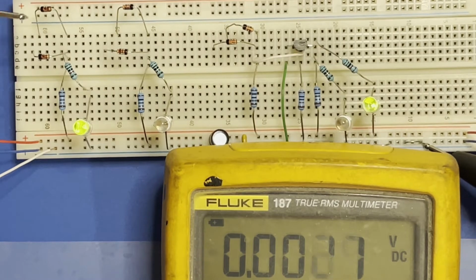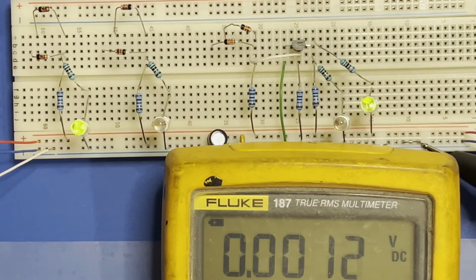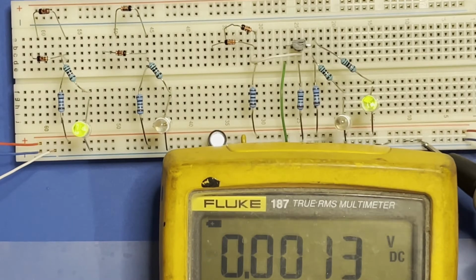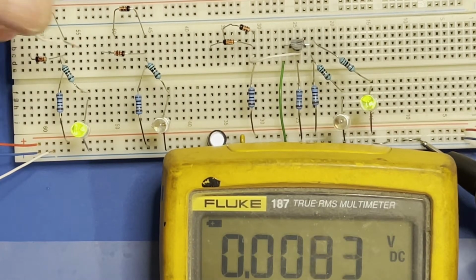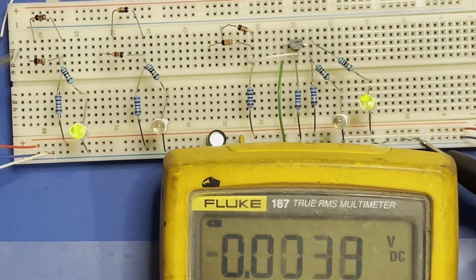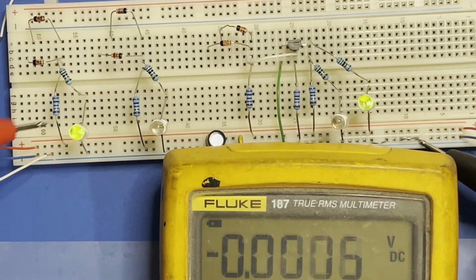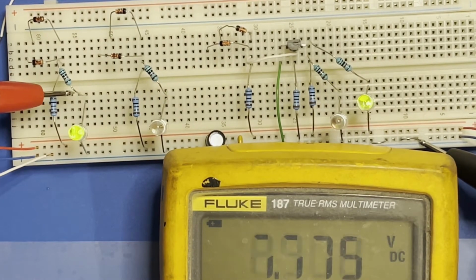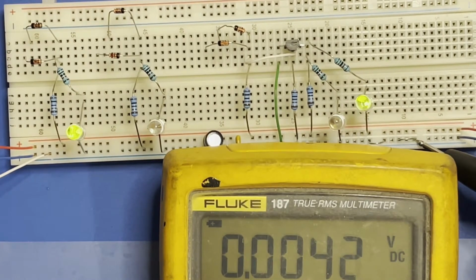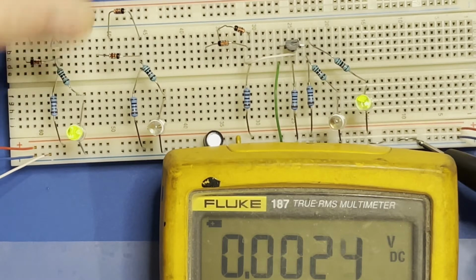So that AND gate is in a one state. Both inputs are floating high. The resistor is pulling it high. So on its own, you'd get the 9 volts, or whatever you supply. But if I cross-connect that to the input of the next gate, that OR gate, because that works the other way around and the resistor's to the opposite side, I'll just demonstrate that first. The output of that is, okay, it's about 8 volts. Power supply is not exact. But you can see the voltage on that. If we connect that output to the input of the next gate, things will go pear-shaped.